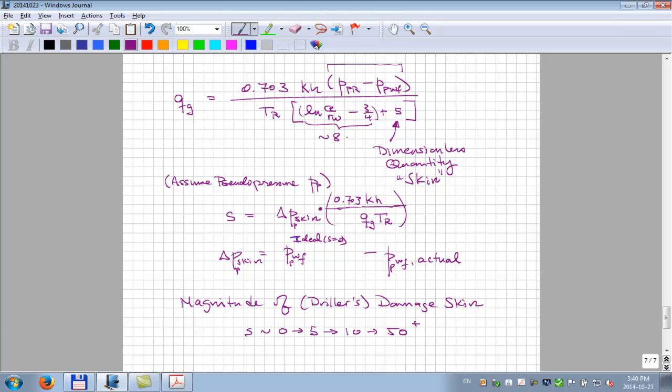Okay, because what it's actually producing is with the 8, right? Whatever it is, you're getting 1,000,000 cubic meters per day here. If I get rid of that 8 that the drilling engineers gave us in the form of a skin, we just go in and put some acid or clean it up, get rid of that permeability reduction. The well now produces 2 million standard cubic meters per day. Okay? And you can start seeing that it has a big effect.